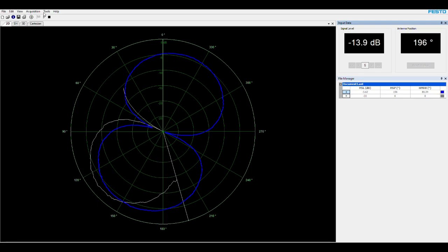Now, as you see, this new measurement that we are performing right now is associated with the case that the dipole axis is not on top of the rotation axis. So as you see, we lose that symmetry that we had in the original pattern. And that demonstrates the importance of making sure that the axis is correct. So you essentially want to measure the same antenna as you are rotating, and you need to be careful about how you place your antenna on the mount. Now our measurement is essentially done. You can compare these two sets of measurements and see how they differ.